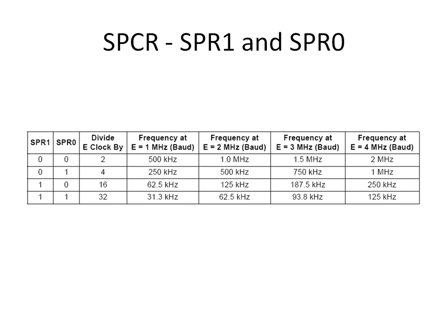Now, looking back at our table, what is the highest speed? Depending on what the E-clock frequency is, what is the frequency of the E-clock? Well, since we're running an 8 megahertz crystal, and it does a divide by 4 internally, our E-clock is running at 2 megahertz. So if we look into that column, the fastest frequency that we can actually send out information at is 1 megahertz.